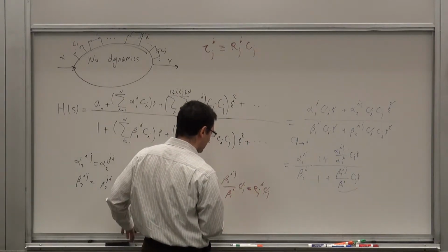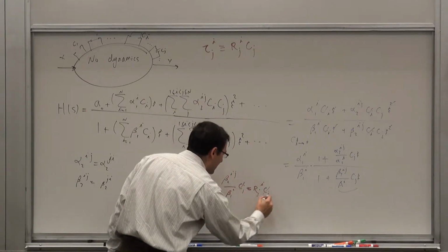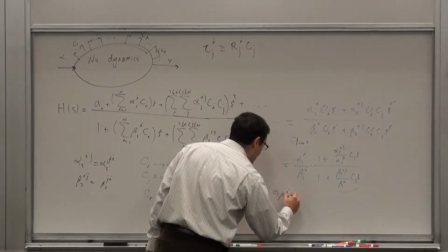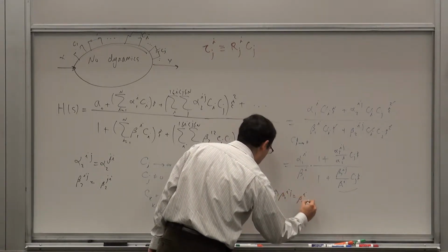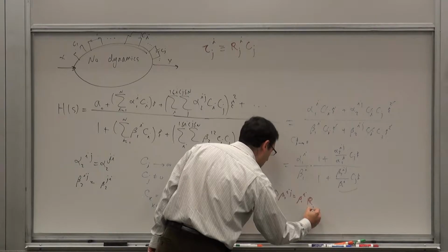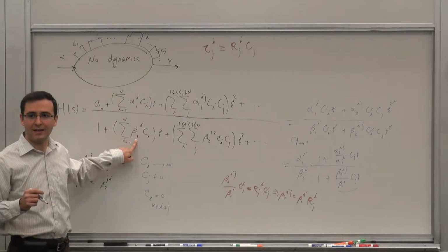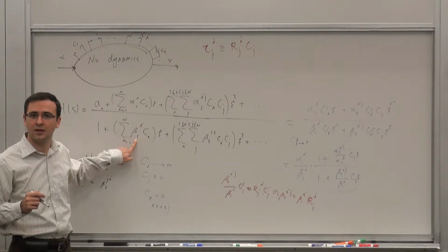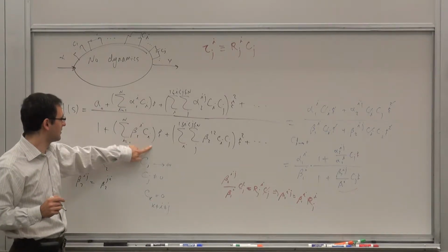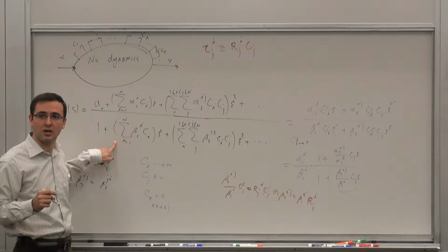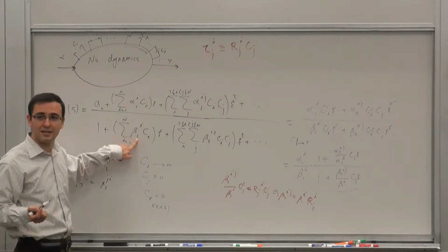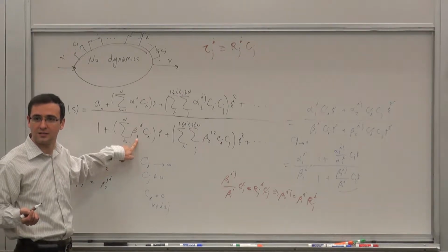So these cancel. What you're left with is that beta 2ij is beta 1i Rji. But what is beta 1i? They have already determined this, right? This is the sum of zero value time constants, B1. So these are Ri0, the zero value resistances.